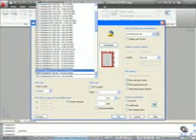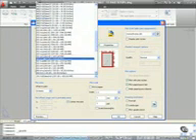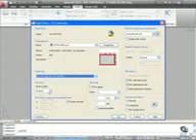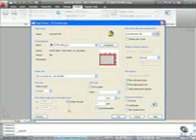So let's scroll up the list here. We've got ISO full bleeds. If I come down a bit, there we go, ISO A3, 420 by 297. You will get a huge list of plotting paper sizes when you use DWF, because the Autodesk DWF file format covers all paper sizes. We're going to plot to extents, so we're going to go right out to the extents of the sheet, and we're going to center the plot on the sheet as well.